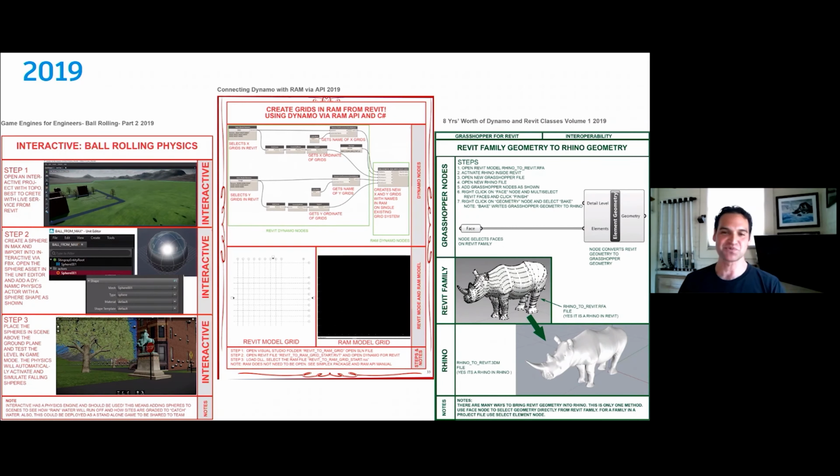One of the examples, to take advantage of physics, was a project where the topography looked flat, but actually was graded a certain way, and there were culverts and drains on one side of the project. We wanted to test whether that topo was modeled correctly based on the civil drawings, as well as where those culverts were.